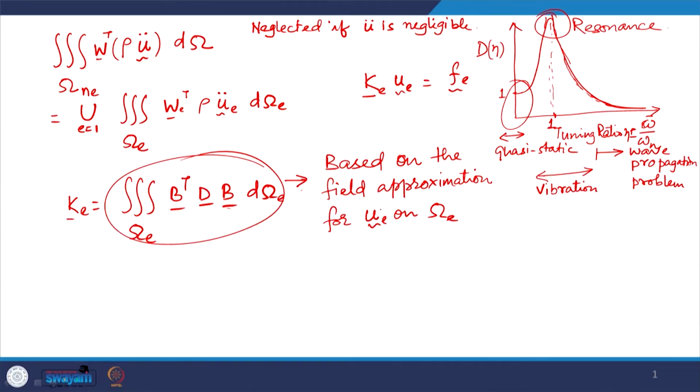or the way we can substitute this displacement approximation in the weak form and we get the same variation if we use the Galerkin approach for choosing the weighting function. So, we arrive at this statement. Now this integral is possible to evaluate because we have a certain variation available for displacement over the element. Now, how do we evaluate this integral involving acceleration? We have variation defined for displacement, but we do not know how accelerations vary over the element.